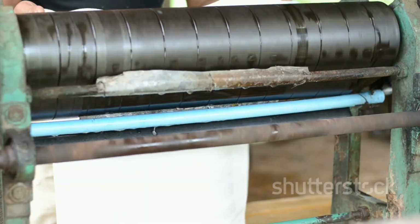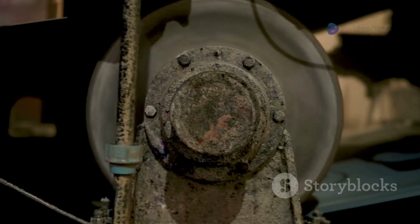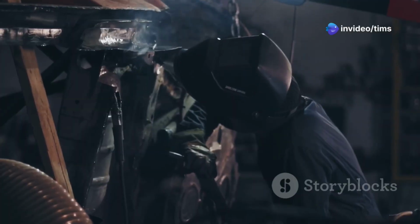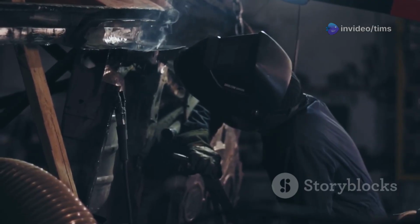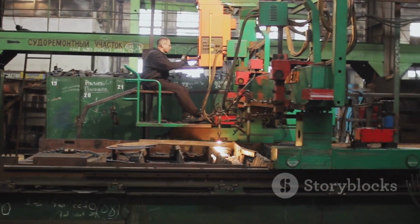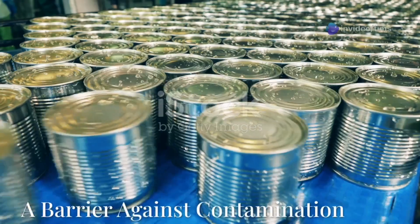Worn or damaged seaming rolls are another common cause of droop. Over time, the rolls can become worn down or develop grooves. These imperfections can prevent the rolls from properly shaping and sealing the seam. Regular maintenance and timely replacement of worn parts are crucial. This ensures the seaming machine operates at peak performance.